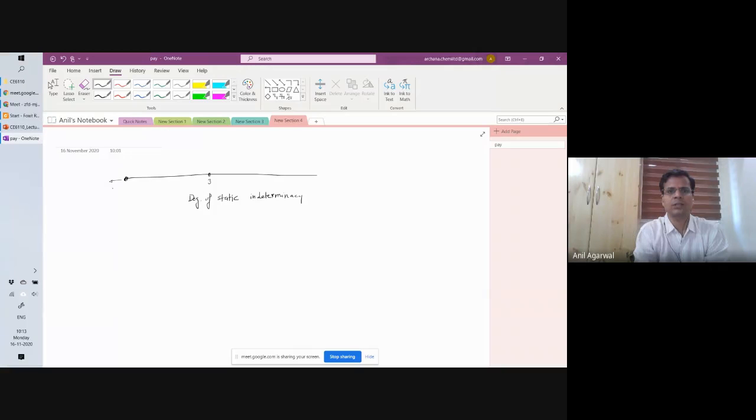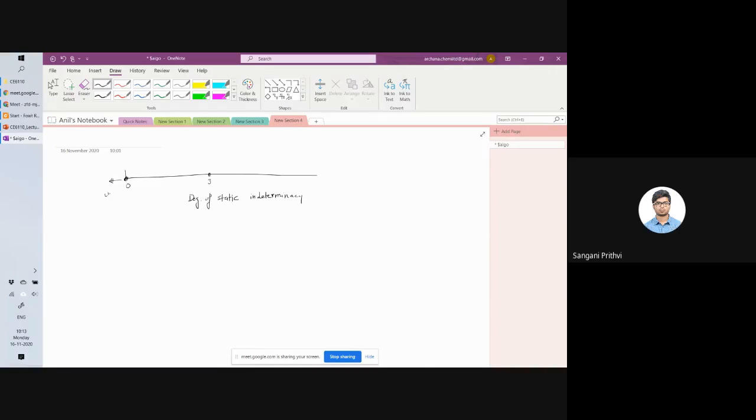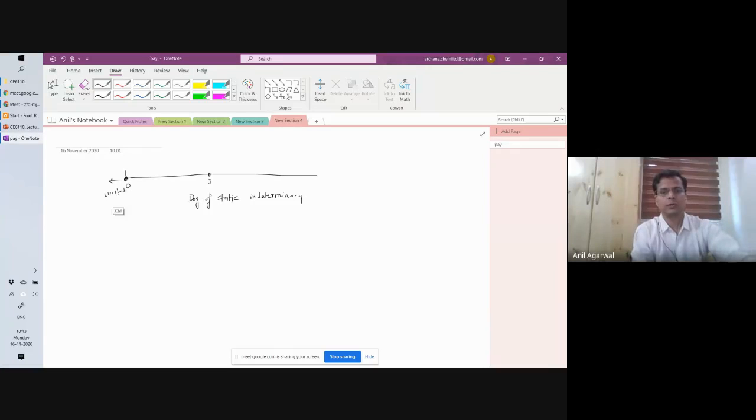Beyond this, behind this point, what do we have? We have instability. An unstable system. This unstable system, you don't want to go there, of course. So the flexibility method says, if this is the system that is given to you, you make it jump here. And in the process, you released 3 forces, that is, you made 3 forces 0. Forces also mean moments here.